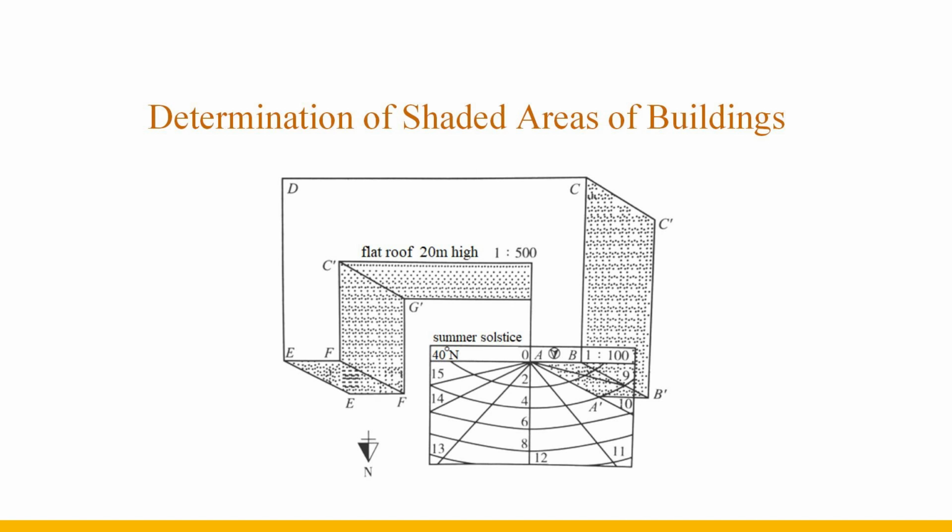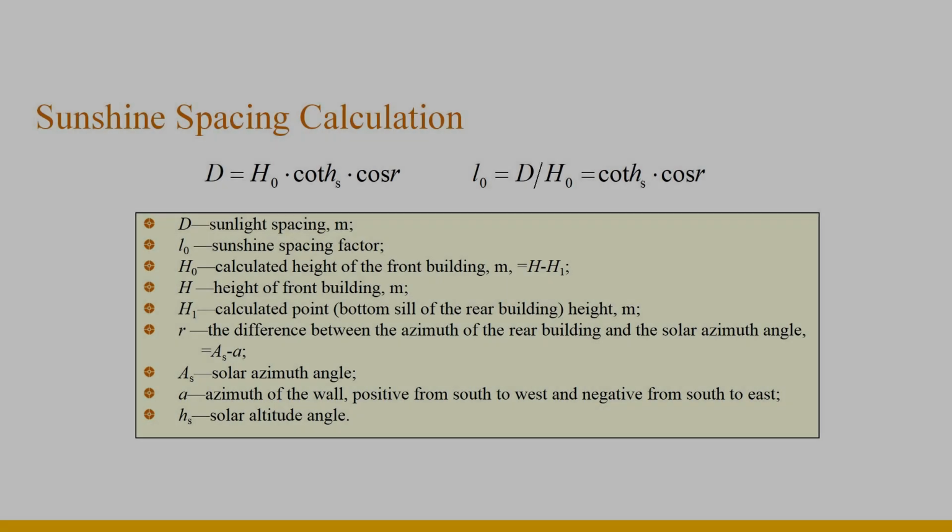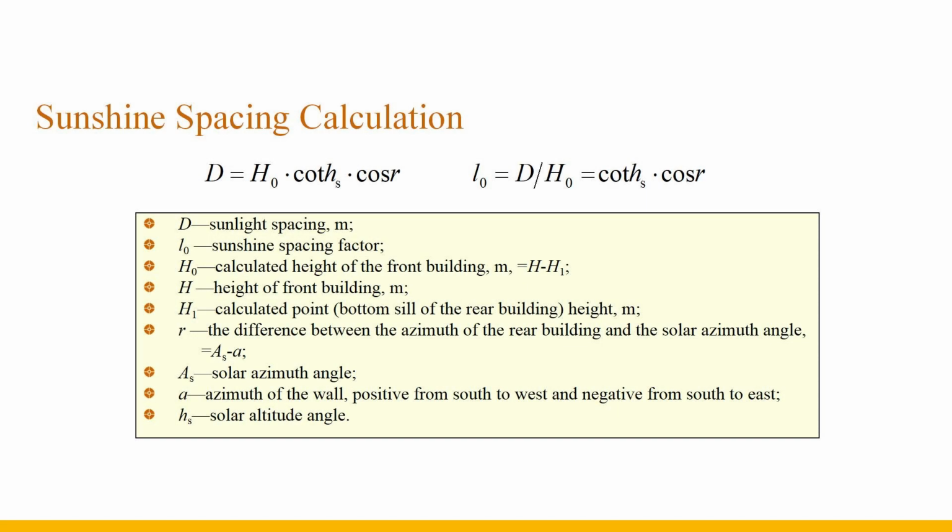Using the same method, place the points B, C, E, F, and C double prime on the point O of the stick shadow chart in order to obtain the shadow lengths, and connect them in sequence to obtain the shadow outline. Using the stick shadow chart, you can also find indoor sun exposure, building spacing, orientation, sun time, seat size, etc.